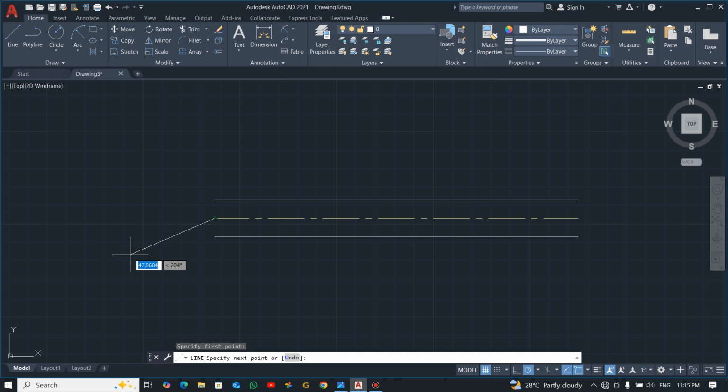So you enter 27, and then after entering 27 you press the tab key to shift to the angle. Now if you watch carefully, the angle on a straight line like this is 180, so we are going to add the 15, which will be 195. So 195.